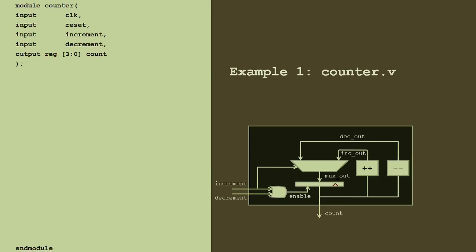We normally don't show in the design that this is a clock or a reset. We know that if there is a register, it will have a clock, and mostly registers have reset. If we know that we don't need a reset, we can initialize it to zero but avoid the reset. It helps at times, but most of the time there will be a reset and clock.